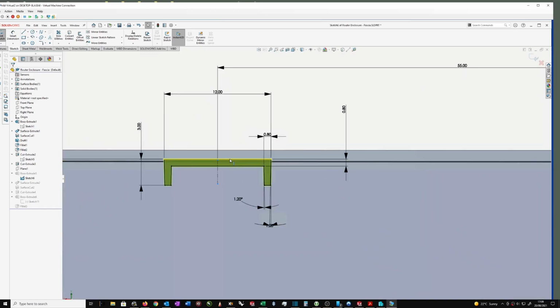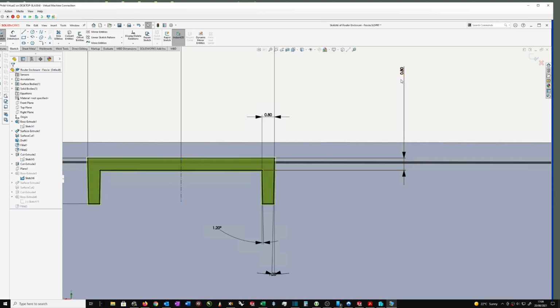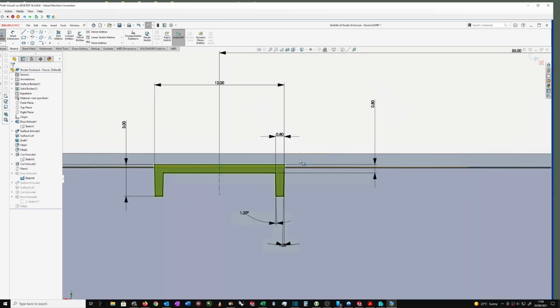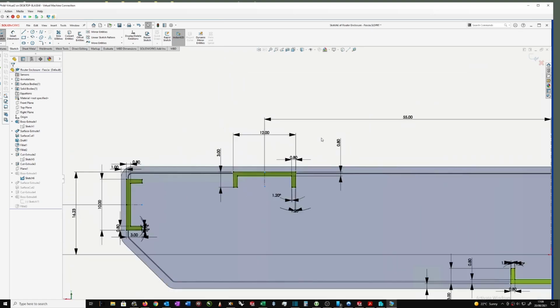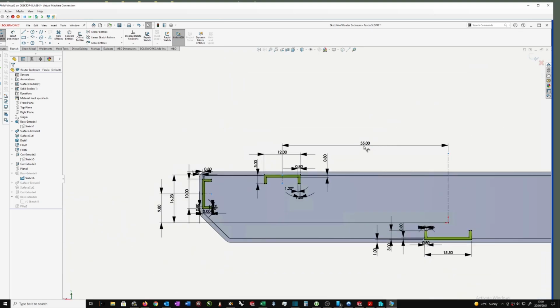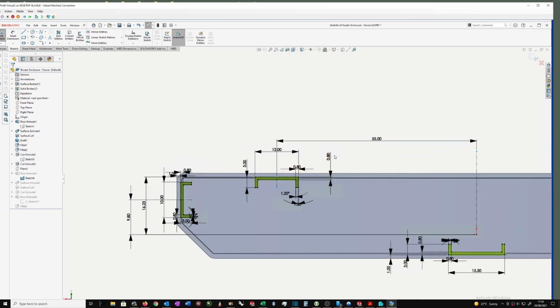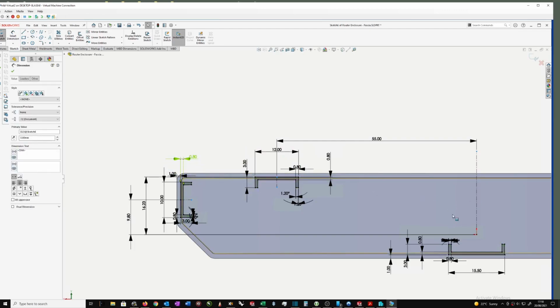So I've lined up that line there with the top line, or it's a certain distance away from something else, so that they interfere and it all works. But some of these dimensions, like this 55, that 0.8, this 0.8, even this 12, most of the dimensions in this drawing are not going to translate well into usable dimensions in the drawing environment.